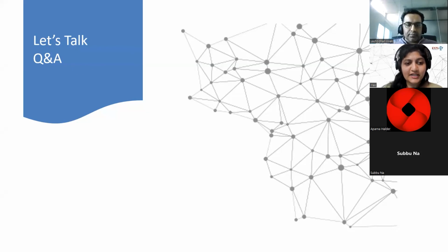Another question is from Harsh. In case we mess up flashing the firmware, can we reset the Diva board to its default configuration? Yes, you can do that. And what is the difference between Bus Pirate and the OCD board? Which OCD board are you referring to? I don't know that, but Bus Pirate is a different thing with different protocols. Bus Pirate has a limitation, I believe it supports I2C and SPI, but here the bus auditor gives all the configurations: SPI, I2C, JTAG and SWD.